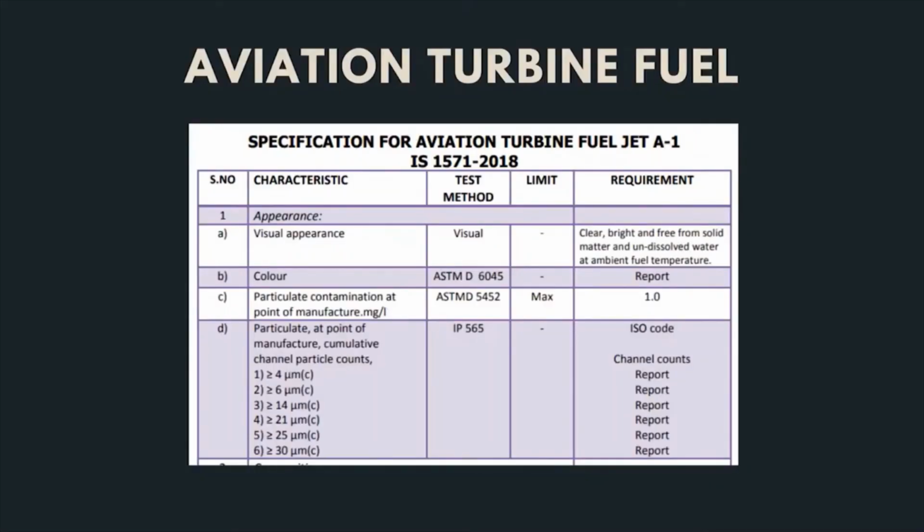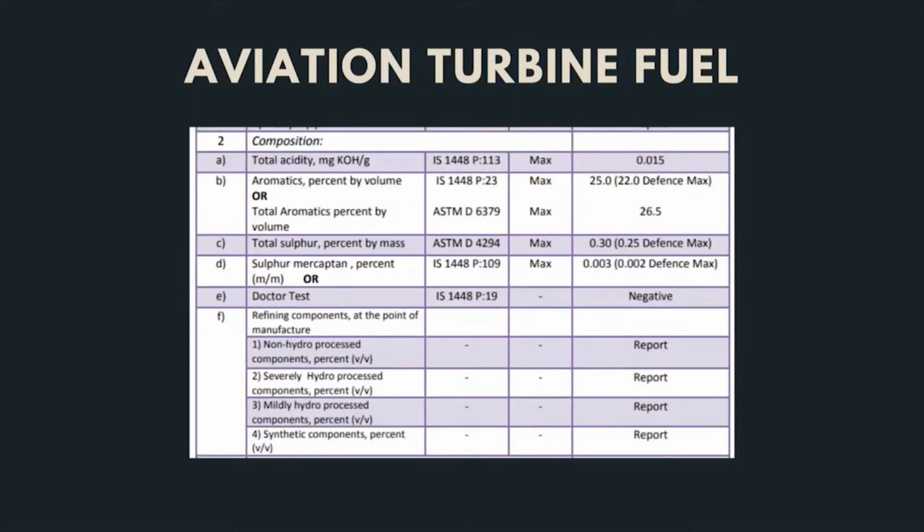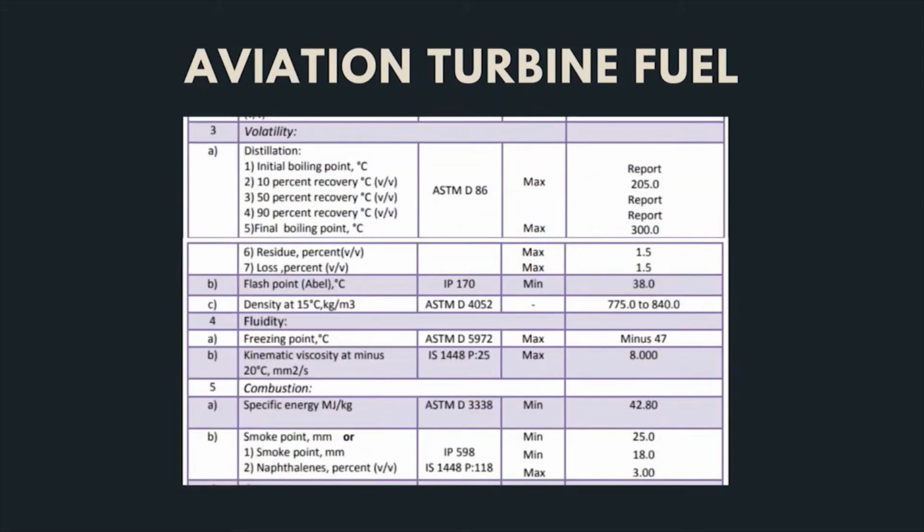Aviation turbine fuel, as I said, has stringent specifications. The boiling point is very important, and a couple of other tests, like the doctor test, the presence of which shows the presence of sulfur compounds. Then flash point is again important, like kerosene.